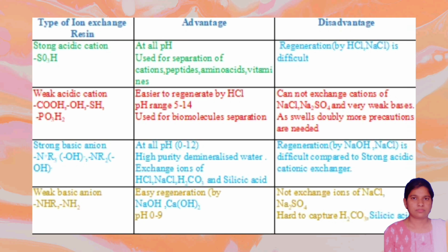Strongly basic anion exchange resins containing quaternary ammonium hydroxide functional groups, which are prepared by chloromethylation of polystyrene followed by reaction with trimethylamine or dimethylethanolamine, are in their chloride form and are first regenerated to their OH form before using them in the demineralization process.